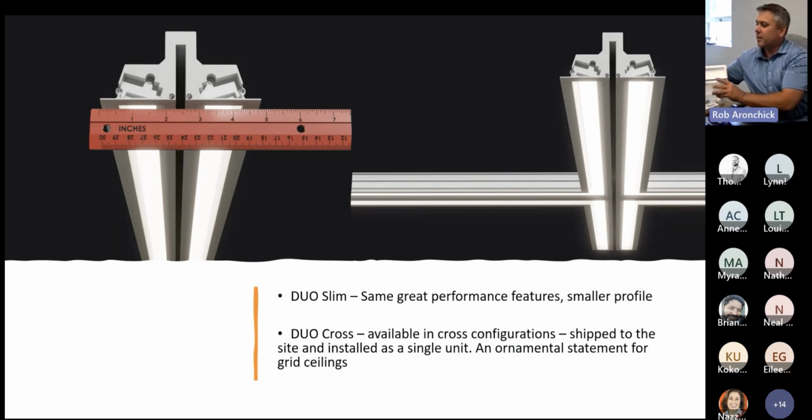We have a slimmer version. So this fixture here that I have on my desk, these are 2-inch lenses on each side of the T. And I want to point out too that the driver sits on the back of the extrusion. So it is an integral driver to the fixture. There's no remote power supply required to install the fixture.